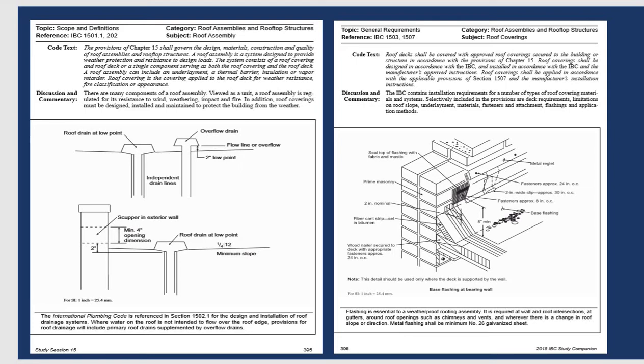And if you look at the top of the roof, you can see some have a design for the drain, and we have different ones for the low points and the overflow drain. When water comes onto the roof, this is the drain to get the water down. So they have a limit of 2 inches from the low point to the overflow. When the water hits this point, it goes to the overflow drain.